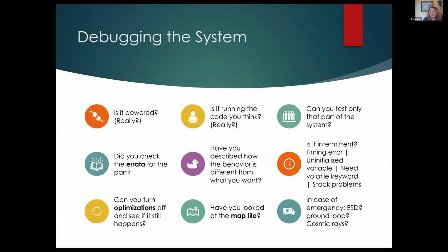Security is very important. My answer for security is don't do it yourself. Many of the processor vendors these days, particularly the ones who are doing Bluetooth or Wi-Fi, already have security built into their systems, including the firmware update system. So security is critical. It needs to be built in from the very beginning, and you need to understand what it's doing. But if you can, don't do it yourself. Use existing security methods that are there for your processor.